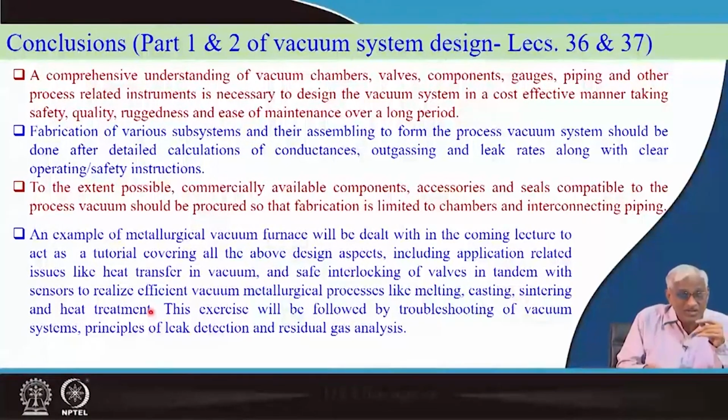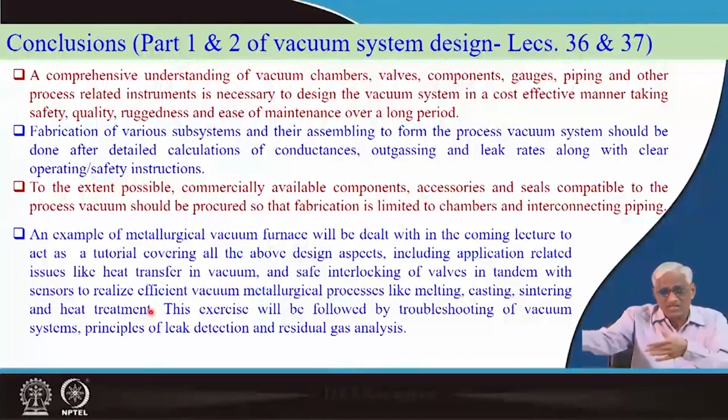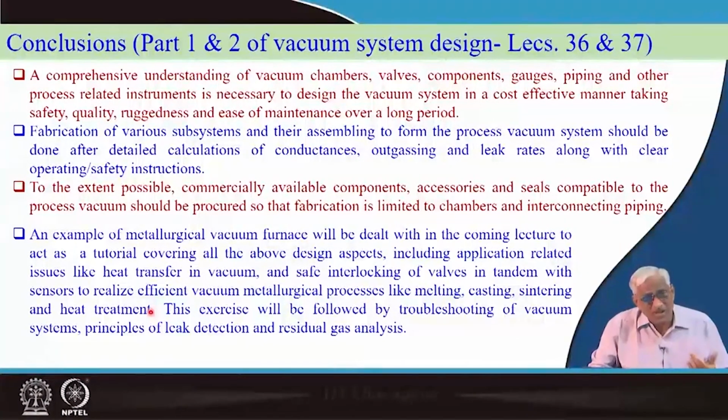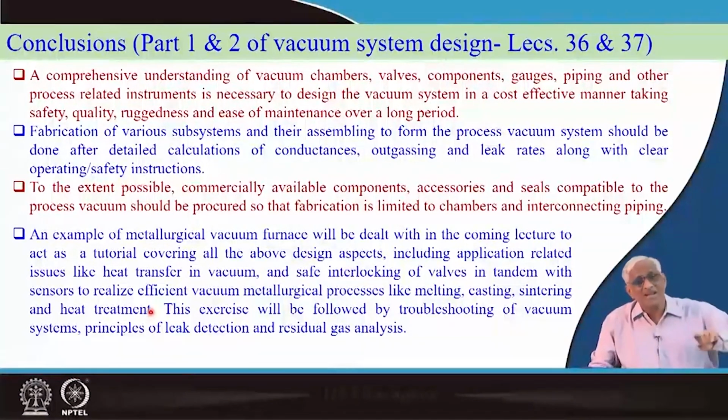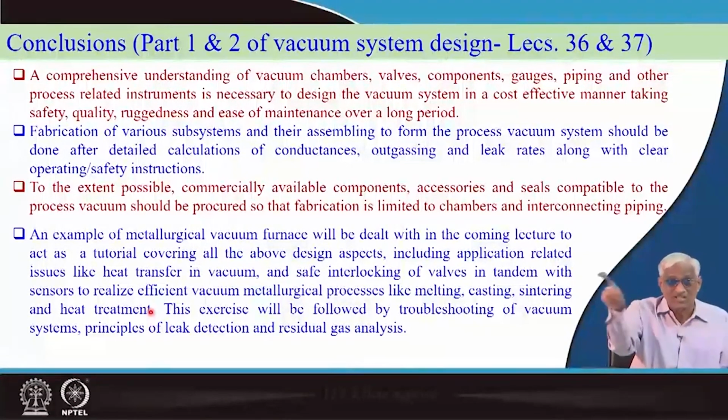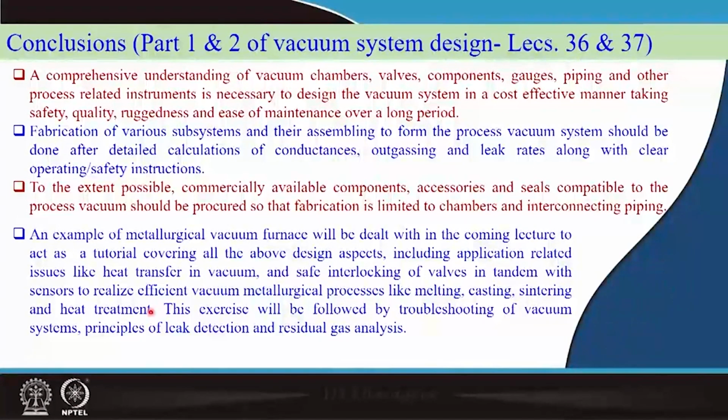I need not worry. These are only routine components in any automobile industry, they need to be heat treated, but they cannot be heat treated in air. It is a heat treating furnace. Okay. Similarly, casting and melting some alloys, aluminum alloys, etc. That is another aspect of furnace, where oxygen should be less. So, the RGA signature should tell us do not melt now.